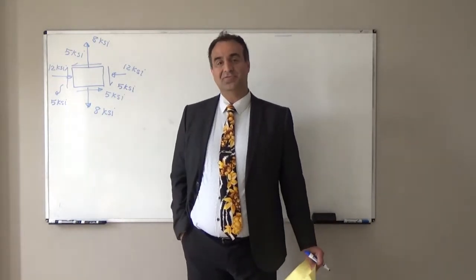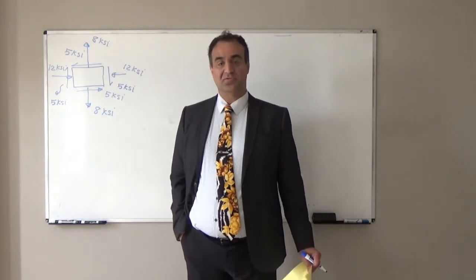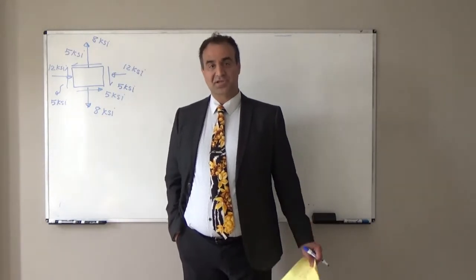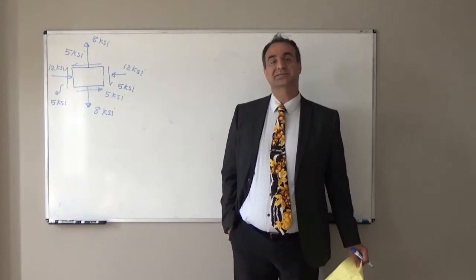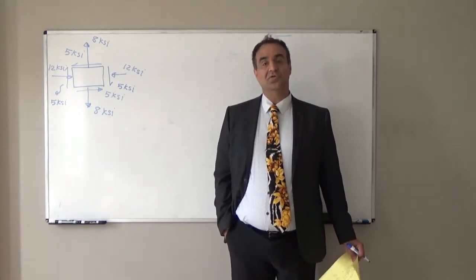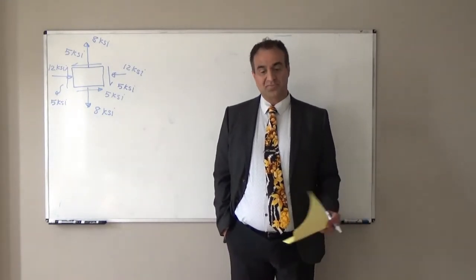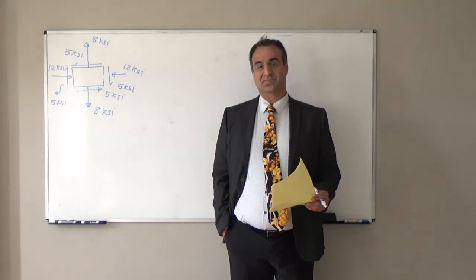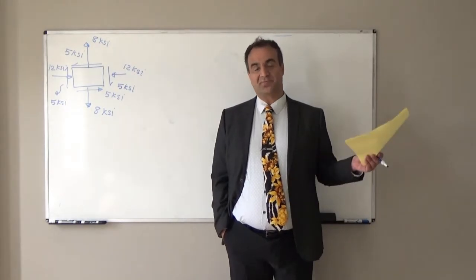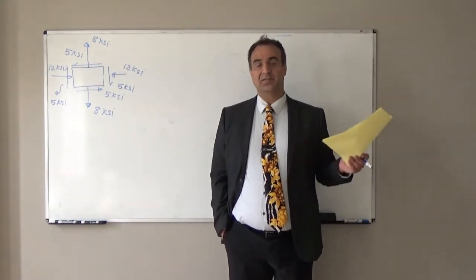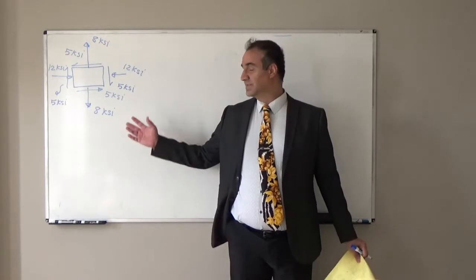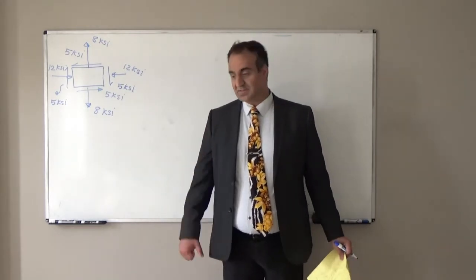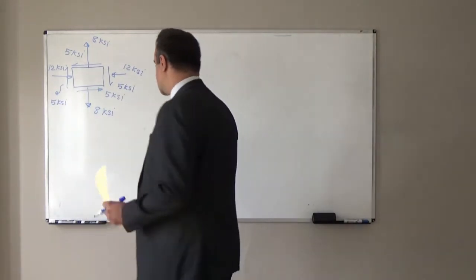What is the magnitude of maximum shear stress? We don't know. In which direction will we have that maximum shear stress? We don't know. In order to answer all these questions, we need to draw the Mohr circle. We need to do stress transformations. We can use the formula I found last session, or we can draw the Mohr circle. Let's look at the Mohr circle.